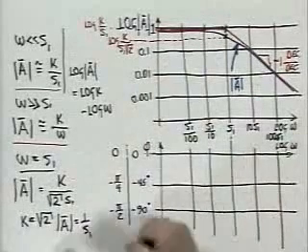The second virtue then of using a log scale for omega, we said earlier it doesn't crowd things up near the origin. The second virtue is it converts functions like 1 over omega, k over omega, which would be hyperbolic on linear coordinates, into straight lines with negative slope on logarithmic coordinates.